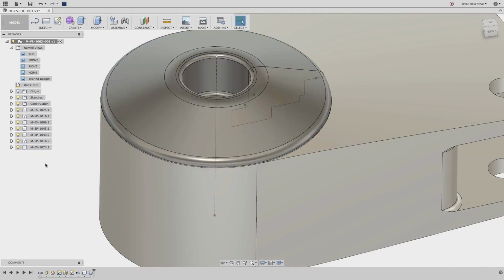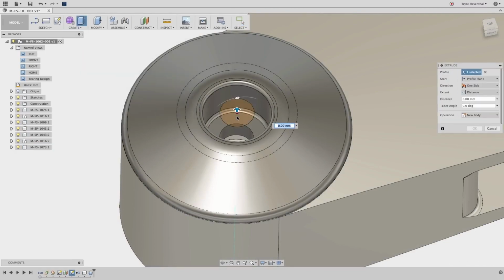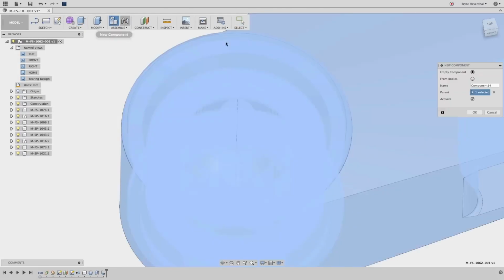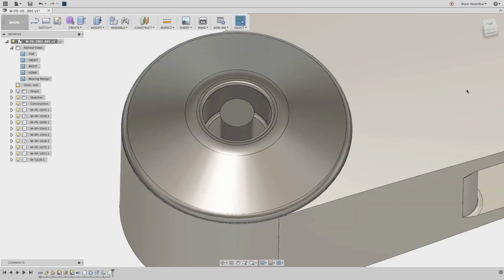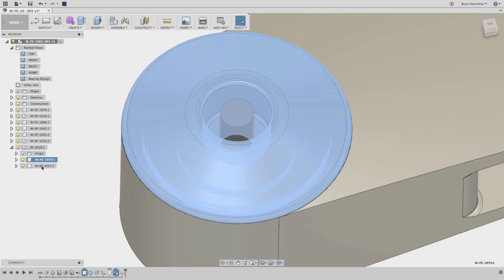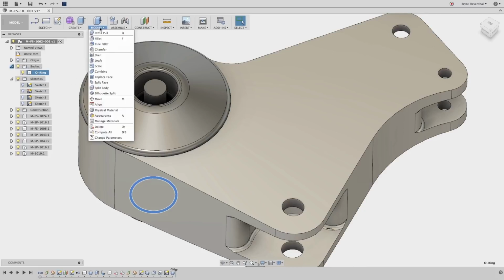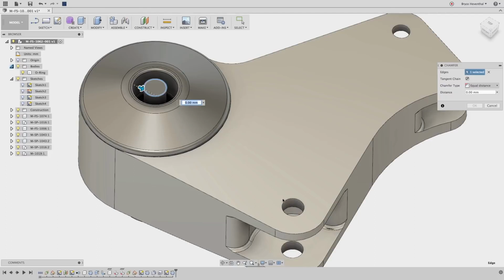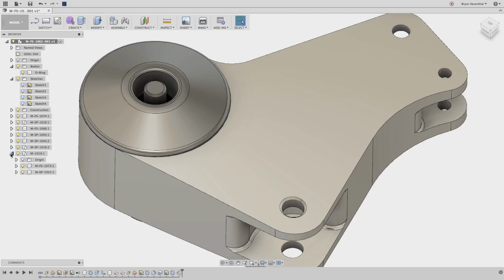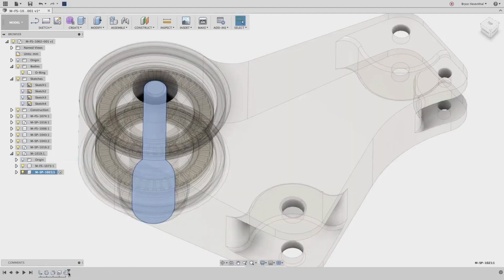Next, let's model another component. Again, referencing geometry between components is fluid and efficient. But what happens when you decide that this component really needs to be two parts that make up a subassembly? It's simply not an issue with Fusion 360. Make components at the point in the design that's most appropriate, and the structure takes care of itself. Sketches, bodies, components, and subassemblies can all live within the same design. And don't worry about placing features on components at the wrong level of an assembly. Even though this component was not set as active, Fusion 360 associated the feature to the component automatically.